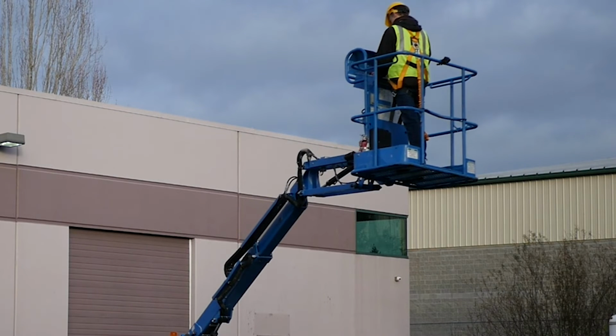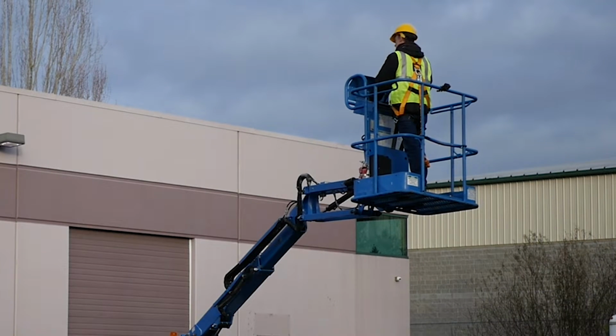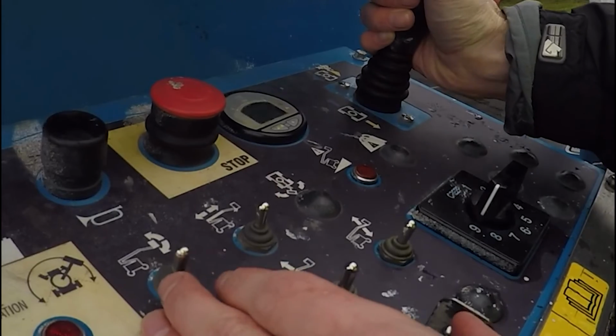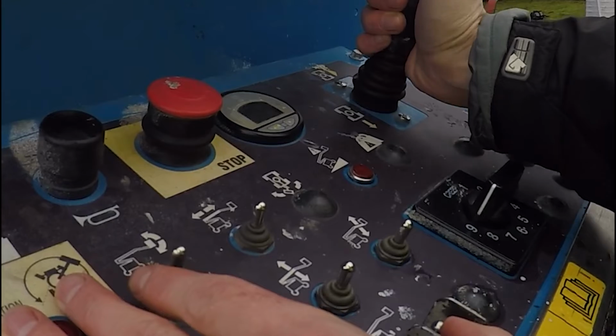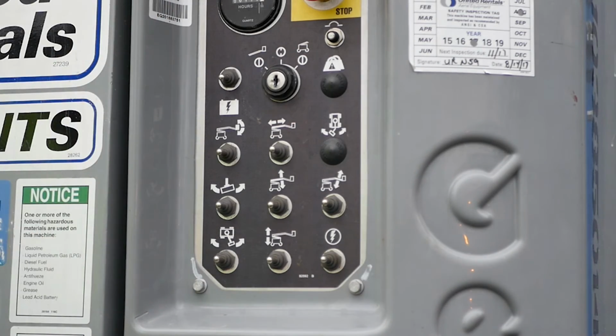When work is complete, shut down the lift, in accordance with the requirements of the operator's manual. Move the boom into the cradled, shut-down position. Make sure the parking brake is set. Secure the vehicle from unauthorized use, by removing, and storing the key.